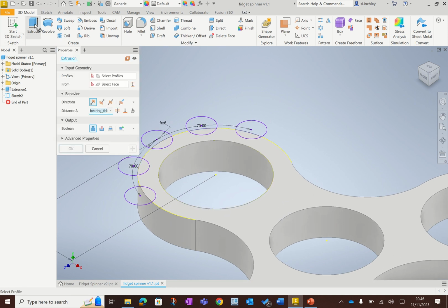Now extrude can add material, as you can see when you hover over these, you click on each one. Oh, I did that wrong. So you can either hold down Control and click back on that circle to take it away. And it's kind of jumped to this one here. And those are the ones I want. So don't hold it on the circle, hover carefully until you find that part highlighted and that part there highlighted, that part there.